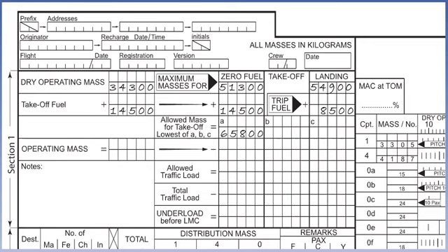Enter in B the regulated takeoff mass, 62,800 kilograms, which in our example corresponds to the maximum structural takeoff mass limitation. The value at C is the takeoff mass that would be achieved if the aeroplane were to land at the regulated landing mass, with the mass of the trip fuel added back to it.